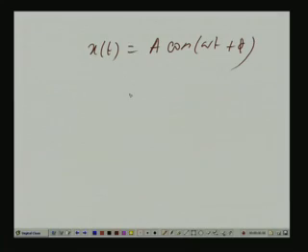I will not call this regular, because this random process is completely described by just a few random parameters, A and phi; omega is fixed. If A and phi are given to you, you know what it is, and it is also predictable, in the sense that suppose you know x(t) for one period fully, or x(t) up to some point of time, say t naught.